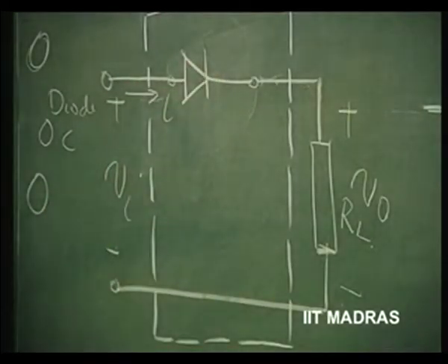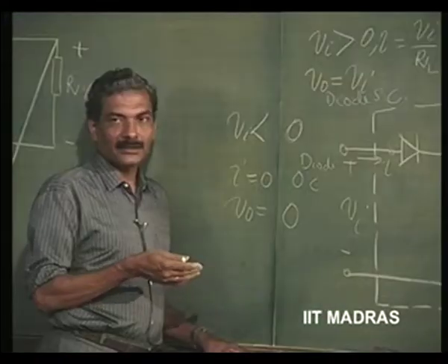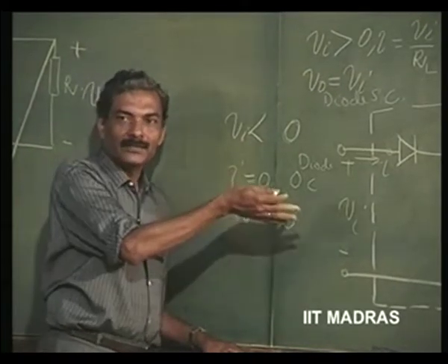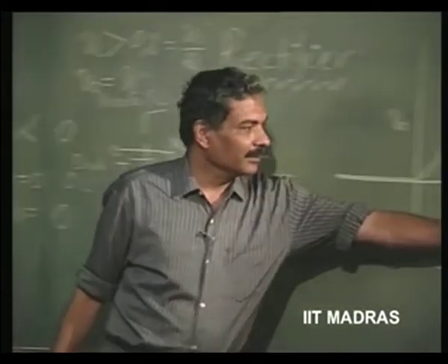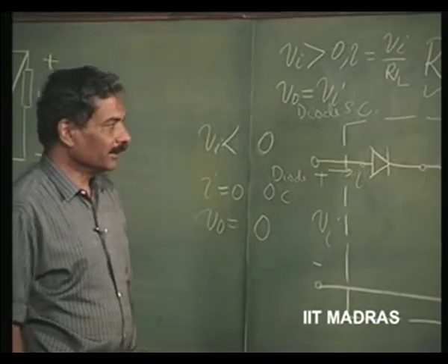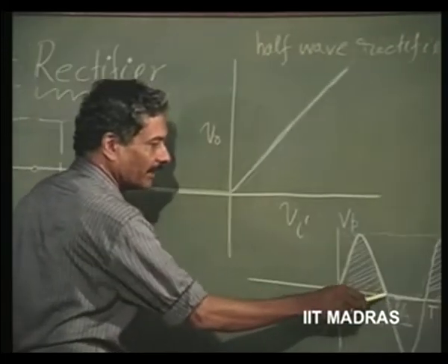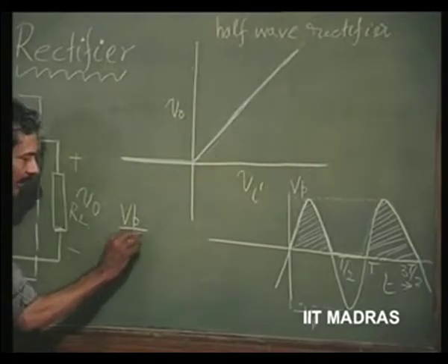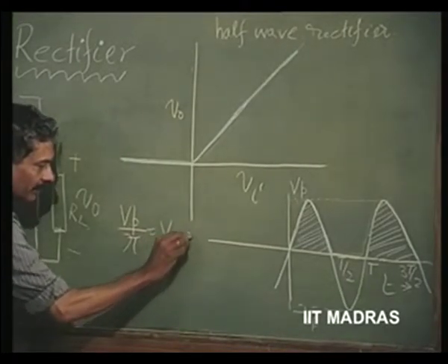A simple application, but one of the widest applications that we can think of for simple unidirectional voltages. You will find that people use just a transformer and a half wave rectifier, and you get simply this unidirectional output, which has a DC component in it, an average component in it. So, this half wave rectified waveform has an average component in it. If you take the average of this, it will come out to be Vp divided by pi as the V average. This is the DC component.